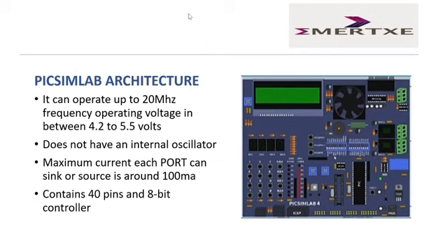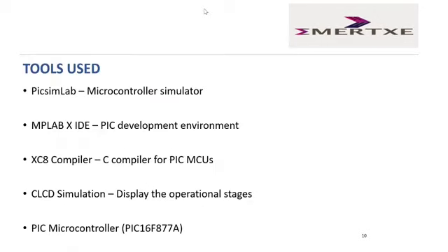And coming to the software tools used: PICSimLab, the microcontroller simulator; MPLAB X IDE, the PIC development environment; XC8 compiler, the C compiler for PIC MCUs; and the LCD simulation displays the operational stages of the microwave oven, with the PIC microcontroller PIC16F877A.